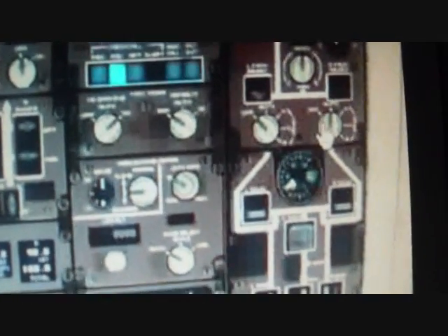You turn on the fuel pumps. Switch the igniters in order to preserve each individual igniter. Now when you actually turn on the engines, you have to turn off the packs to get most air into the pneumatic starter, and then you switch to ground.